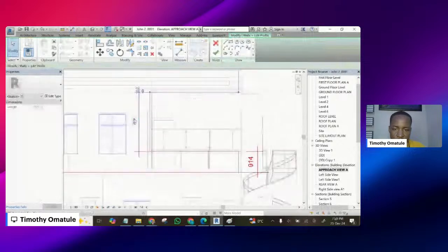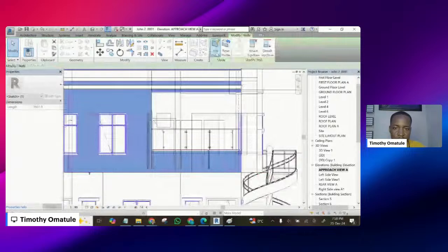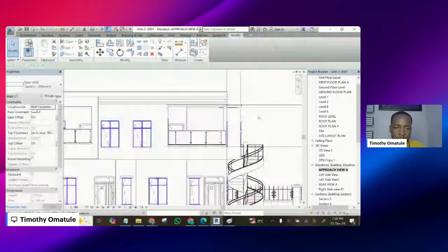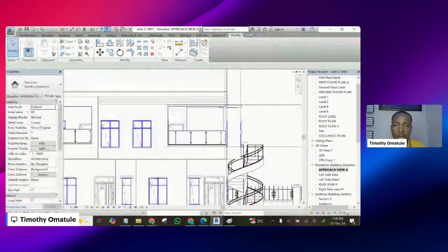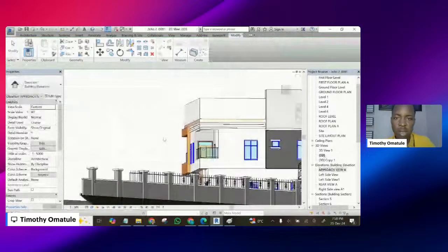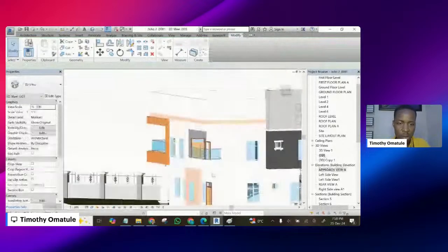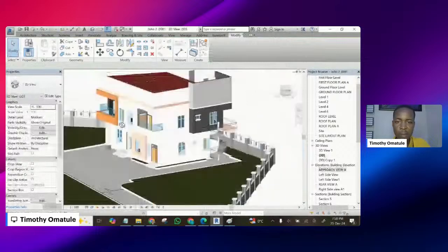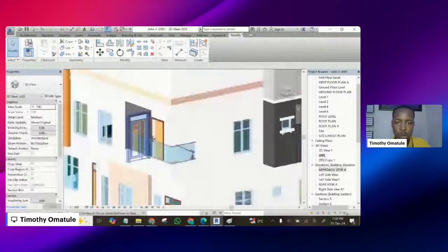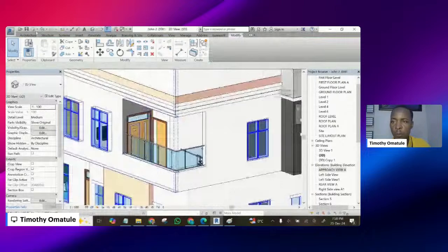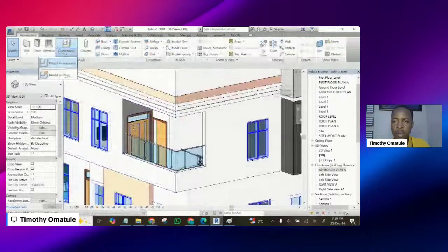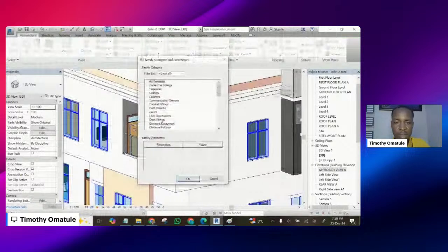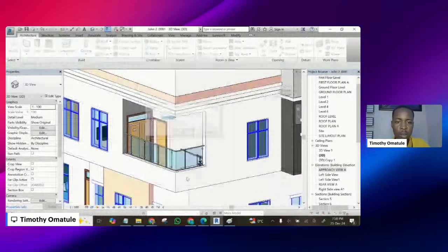Make this one 2537 so that they are exactly the same. Okay, so now I can try my extrusion now, since I see that they are the same now. So I simply go to architecture, select component, model in place, casework, click OK, then click OK again.